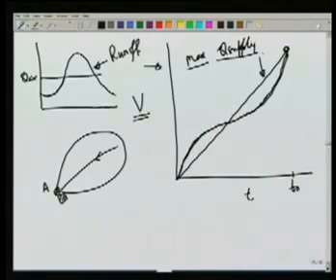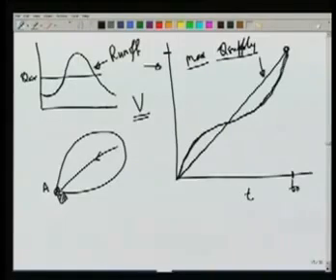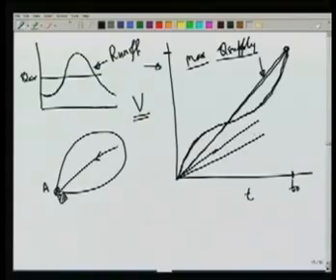this is the maximum rate at which we can supply water, because this is the total amount of water available to us. V is the total amount of water available to us in time t0. We cannot supply more than this water. So this is our maximum rate of supply. Less than that, of course, we can always supply, so we can always supply anything at a smaller slope, but more than that we will not unless we take water from somewhere else. So let's say that we want to supply this maximum rate by creating some storage facility here. The question which is to be answered is, what should be the capacity of that storage structure?